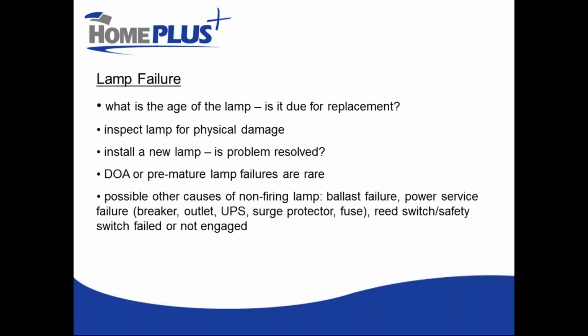So if we have a case where we have really low contact time, the only way we can compensate for that to achieve our same chlorine dosage that we're targeting is to up the chlorine level. Generally speaking, I would say anything over 1 part per million or 1 milligram per liter would be considered high and probably higher than desirable.